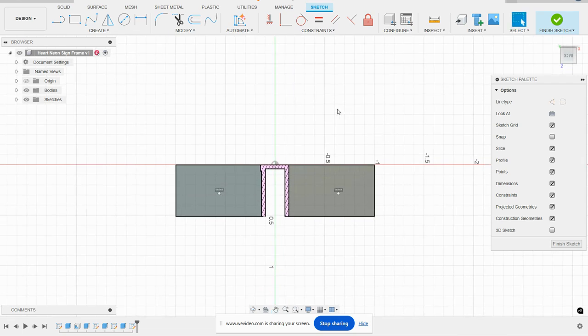All right, so the actual holes in the box are 1.5 inches apart. So let's say this point to this point needs to be 1.5 inches away from each other. The total bracket itself is 2. So that means we have a difference of 0.5, which we divide by 2, meaning that from here to here, this needs to be 1/4 of an inch, just like so.